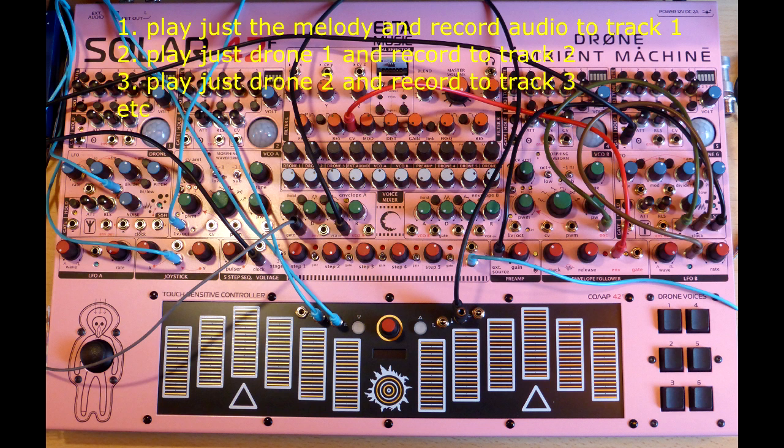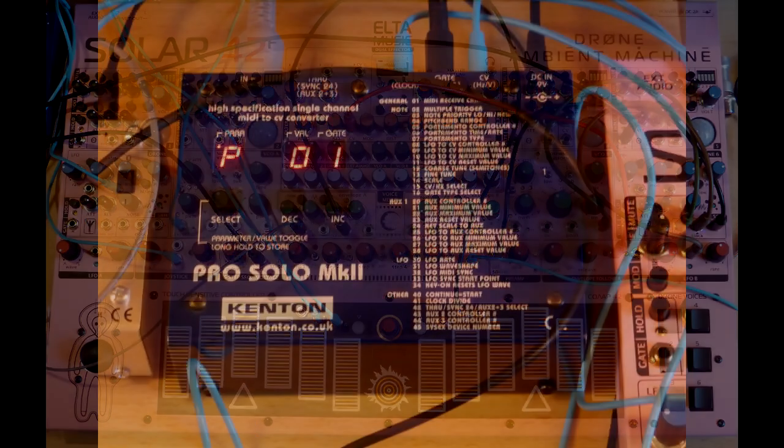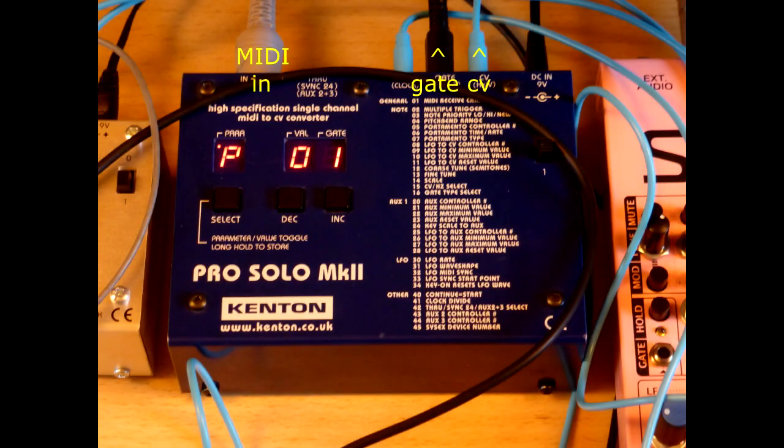The MPC gates generate 5 volts, but the step sequencer needs at least 5.6 volts to trigger. I found this by experiment, but apparently it's not consistent across machines. Other users have found they need even higher voltages. The level converters are usually available on traditional modular synths. I don't have one handy, but this Kenton Pro Solo MIDI to CV converter has a convenient auxiliary output which can generate gate voltages at any level from incoming MIDI clock messages.